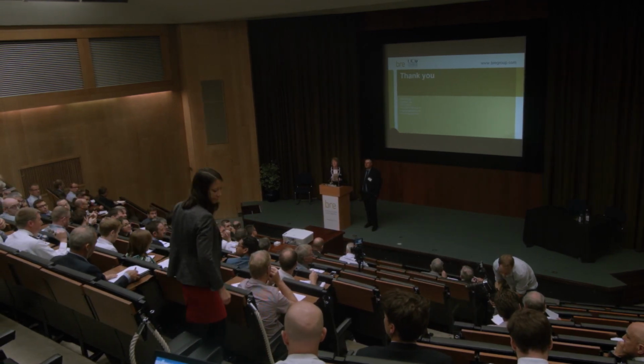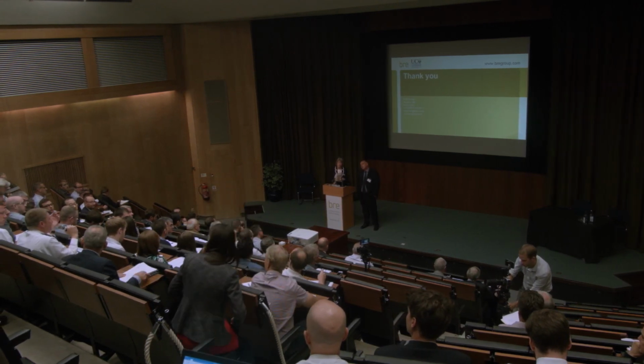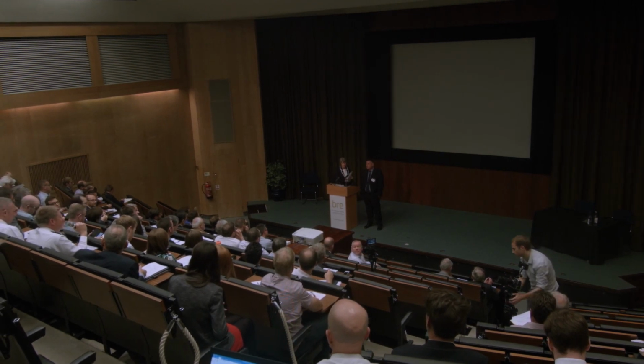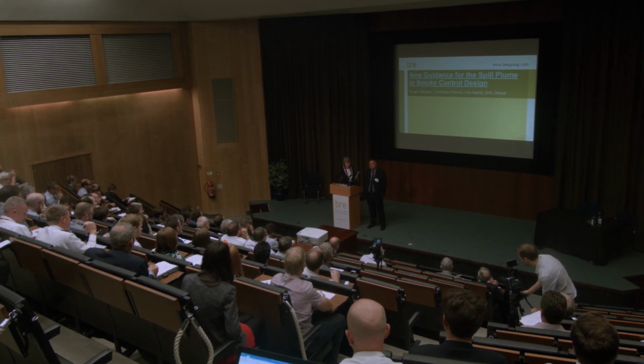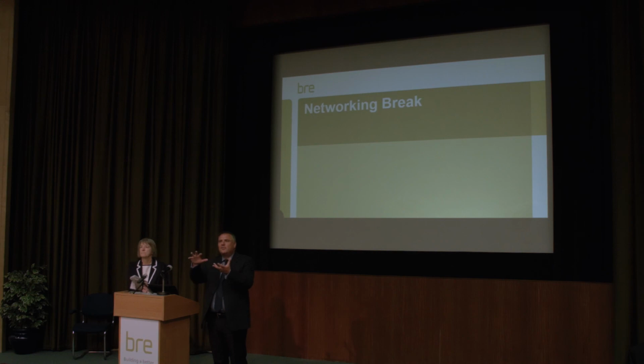Thank you. Bob Birtles, Greater Manchester Fire Service. Do normal atmospheric conditions impact on the behaviour of the plume, like temperature, pollution, humidity? Typically, the fire size is in there, but typically we're looking at temperature above ambient. So I did my experiments over a range of months and different background temperature conditions, but usually it's the temperature above ambient in terms of the buoyancy. So typically not. And things like humidity, I think it's probably insignificant, really.